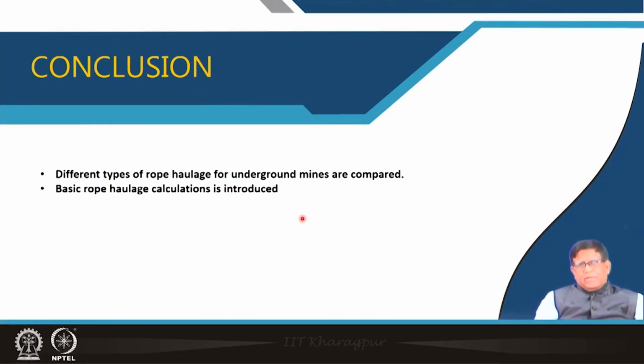Take up how to do the motor power calculations for driving a rope haulage. If you can prepare a simple Excel based calculation model using the equations given in this class, it will be useful for you to construct knowledge. So, we have just compared different types of rope haulage for underground mines, and we have discussed it. The basic rope haulage calculation is also introduced to you.